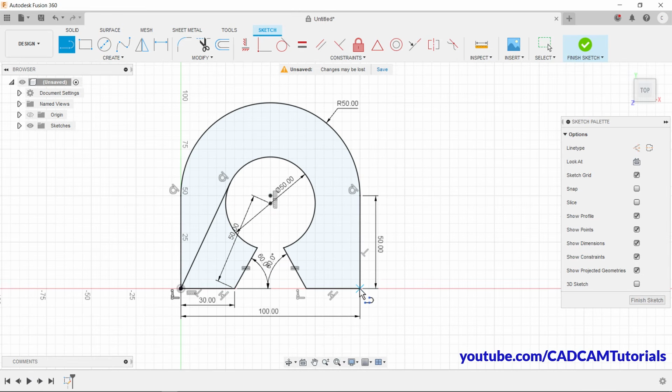In the same way, suppose I will again click here. Suppose my line is like this. I will create it in empty space. Okay, right click, cancel. And if you want to apply a tangent constraint here, then for that click here on tangent, click on this circle and this line. So here this tangent constraint got applied. So in this way also you can apply tangent constraint. Then trim it, trim and click, right click, cancel. So in this way you can create tangent lines also.